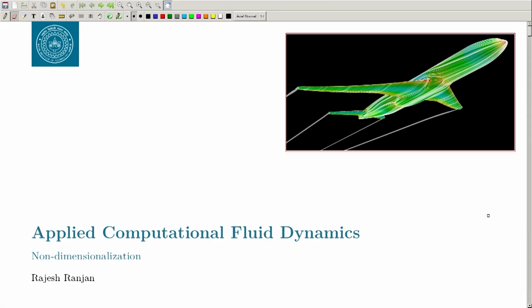But before it was designed, the parameters must have been evaluated in the wind tunnel. Now, fitting that kind of aircraft in a wind tunnel is very difficult. The size is too big, and in order to exclude the wall effects and other things, you need a wind tunnel which is at least 4 times the size of the aircraft, and building that wind tunnel itself is very expensive.